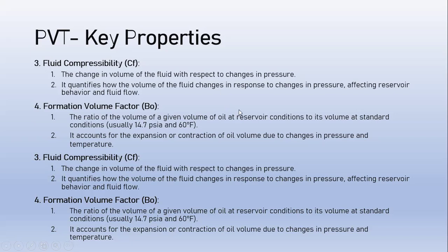Formation volume factor is more of a shrinkage factor. It accounts for the expansion or contraction of the oil volume due to changes in pressure and temperature. Usually the volume within the reservoir is not the same volume you will get at the surface due to gas liberation.